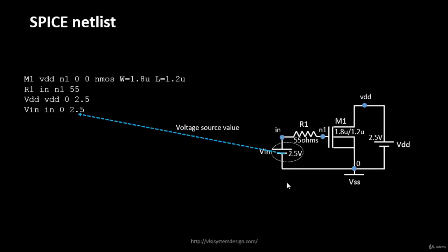Things become a bit complex when we have more transistors, because writing this SPICE netlist manually might be difficult. When there are multi-million transistors, writing down the netlist for each and every one of them will be tedious. We'll look into how we tackle that problem as well. But once you look at a single line in this SPICE netlist, this is what it exactly means. There are other complex notions of the SPICE syntax as well, which will come when we go into complete circuit design.